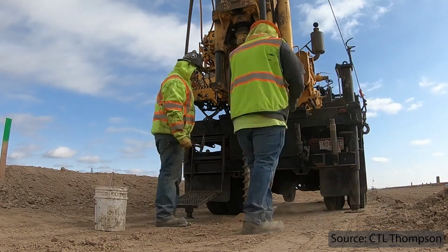So that's why we have to do test boreholes and design, because what you've got at the bridge site is what you've got. You've got to design around it. And that's why the foundations for a seismically resilient bridge can be an extensive part of the cost of the bridge and just an extensive part of the construction of the bridge.